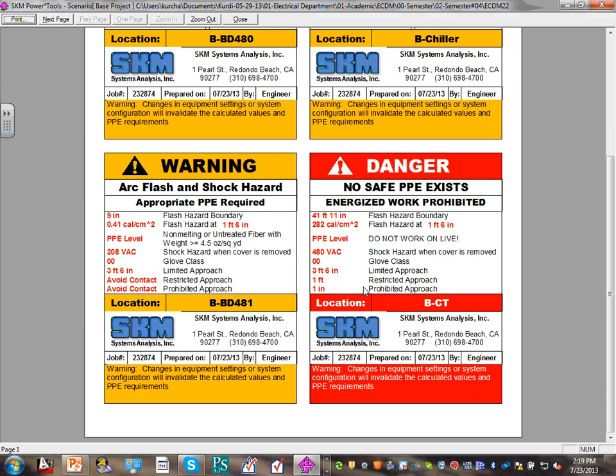Again, the rule is de-energize first. I'm laughing because there's a lot of issues that could happen. So when you want to torque your equipment, you want to work on it de-energized. But if you were to work on it energized, these are the so-called shock hazard, and right above them is the arc flash hazard. So you can see there's nothing here.